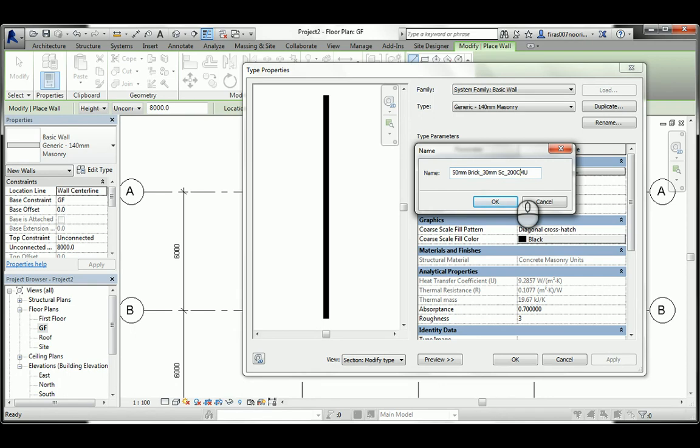And you can just go here and double M, and then finally I can go underscore again, and then 20 mil of a gypsum board. I think the standard is 13, but it's just me assuming the whole thing. And I highly advise you to put your name here after that, so you know later on when you design that this wall was created by you, so you can use it and depend on it more, because it's the one you created.